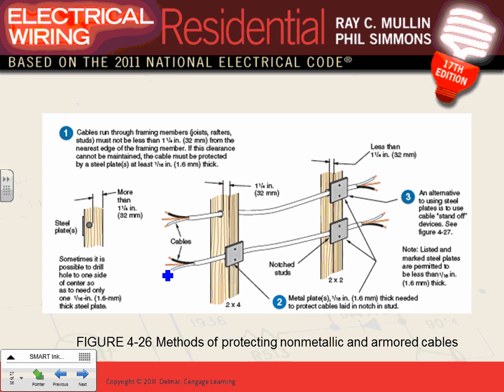A couple of things you have to maintain if you're doing residential, and I'm moving a little bit fast on some of these, guys. Here's the hole that you drill, either in metal or in studs. You have to maintain 1.25 inches from the edge as you drill. Everybody knows that? Why? Because you don't want the sheetrockers to put their screws right through the cable.